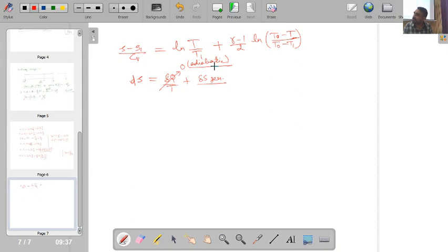So this ds, whatever entropy change we calculate for flow with friction, is equal to delta S generation, and delta S generation is always greater than or equal to 0. So ds for the flow with friction has to be greater than or equal to 0. So whatever S minus S1 we are calculating always has to be greater than or equal to 0. It is very clear that whenever a fluid flows inside a pipe with friction, its entropy will always increase. This is one important conclusion we have made here.